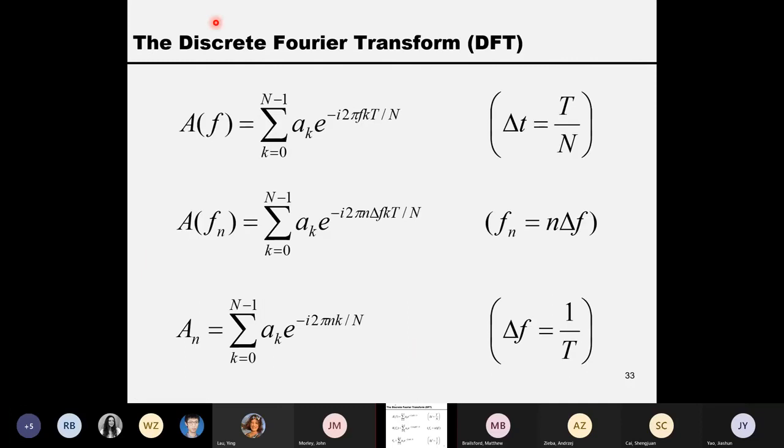Remember, at the beginning when we talked about the Z transform, well, let me repeat it. When we do the Z transform, we transform a time series, which is n samples, into a single function, right? So that's the f here, a smooth function. But now we digitize f into a series of digitized frequencies. So now basically we go back to a series again. But this series is in the frequency domain. From the previous series in the time domain, it now becomes a series in the frequency domain, right? So this is straightforward. Okay.